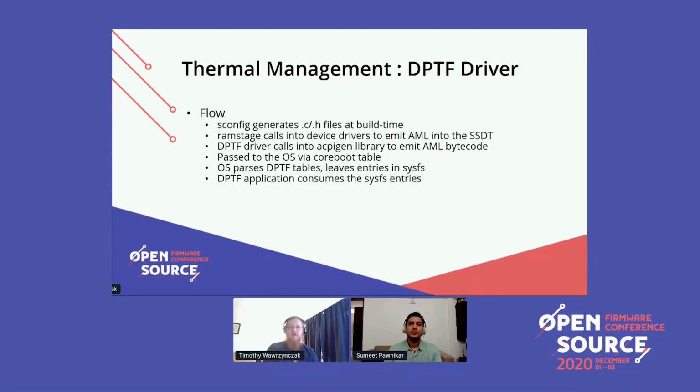During RAM stage, when memory is up, we'll call into all these device drivers to emit AML, which is ACPI machine language, into the SSDT. The DPTF driver will call into the ACPI gen library to emit the AML bytecode.